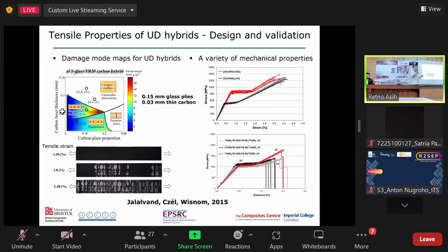Since we use a prepreg, we bought it from Toray and also SK Chemical. So it's an epoxy base that we use here. We cure it at 125 degrees, and after curing we examine it under optical microscopy. Before we put this tensile loading, there's no phase variation after curing.